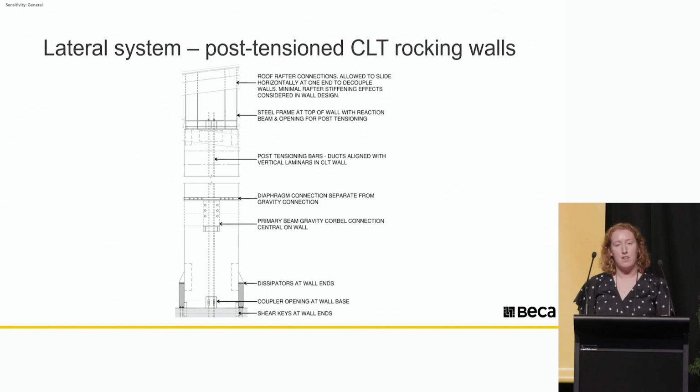As this project did not have a low damage requirement, we focused on providing economic and robust connections, which built in redundancy, and we investigated the consequences of large rotations. The post-tensioning level was one of the key factors of the analysis. And for this, we needed to find the sweet spot between over-tensioning the walls and ensuring the walls didn't start rocking on a windy day.